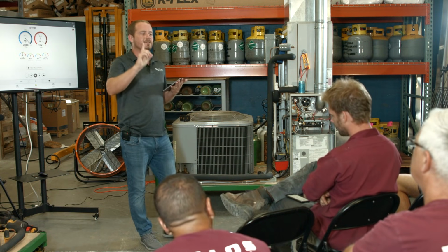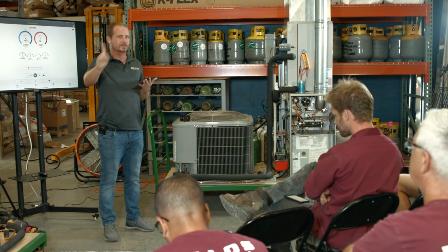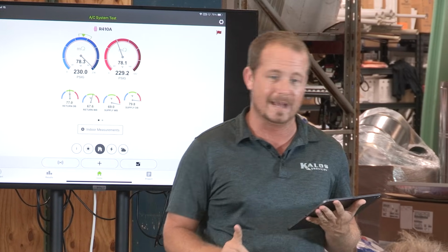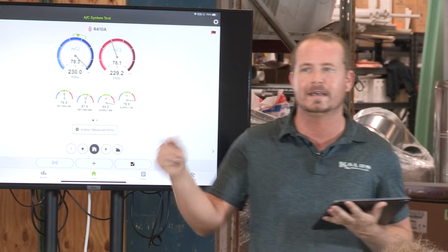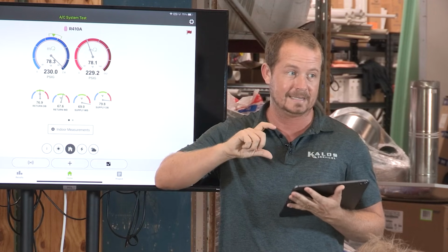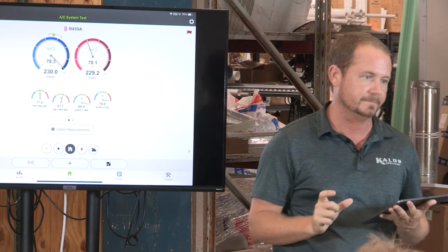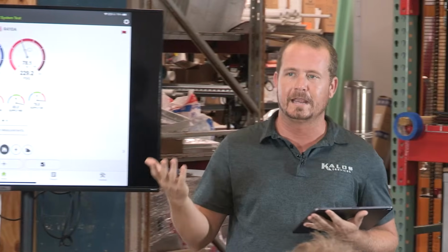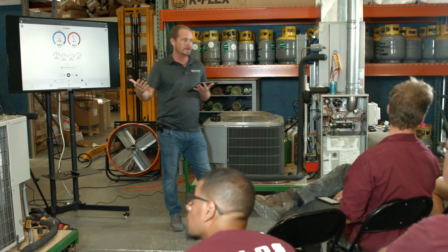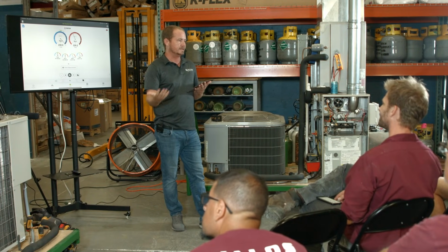If you actually have liquid making it back to the compressor, that's a flooded condition, running flooded. But in that case, your mass is not lower. Your mass is much higher, to the extent that the compressor can't even compress it. If it were to get into the compression chamber, it would explode the compressor head, right? So there's this fine line between light gas coming back and wet gas coming back that causes damage. But we're assuming here that we have some superheat, and so it is dry gas.